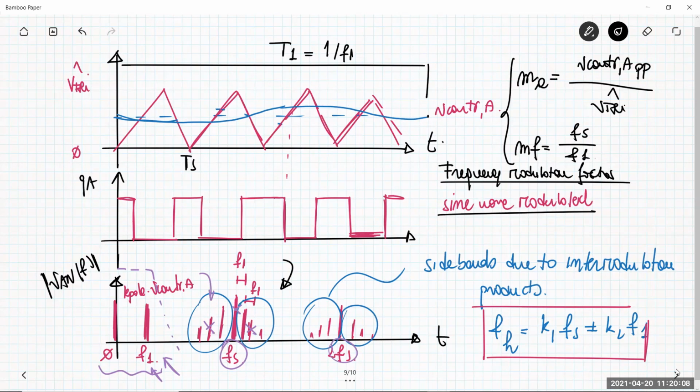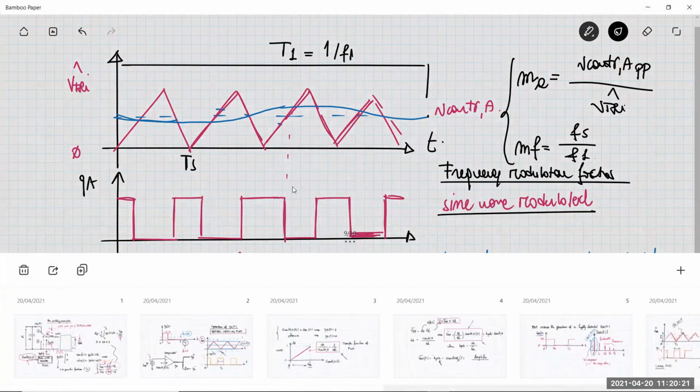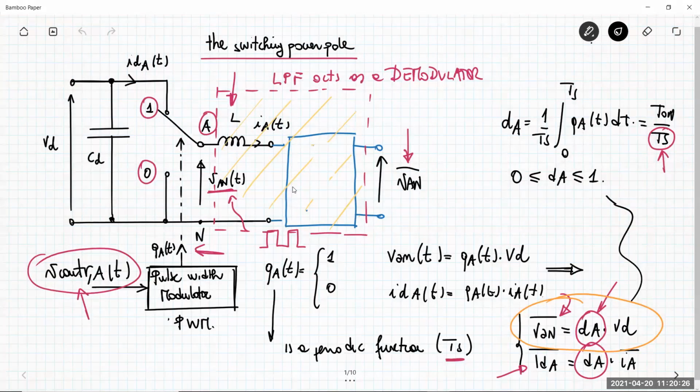Typically, a situation that you can have in a motor application, driving motor application, is that, let me go to this slide here, I said you have to put the modulator here. This demodulator, that also includes L, acts as a low-pass filter in order to get what I'm interested in, which is something very close to the origin of the axis between the DC part or DC plus the frequency F1 in case of sinusoidal control voltage.